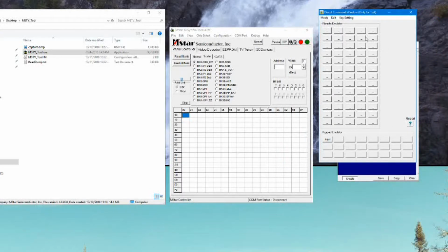So you can think of it as actually laid out as a cheap Chinese generic remote control. By futzing through these, you can figure out which button does what. One of them will actually open a full-on TV OSD menu where you can change things like aspect ratio, color, contrast, as well as being able to change inputs to inputs that weren't previously available. For example, if you select the component inputs instead of RGB, if you feed component into the Scart connector, it will actually properly scale it and output it over HDMI, which previously wasn't a feature I was able to get to work without manually selecting a component input using these